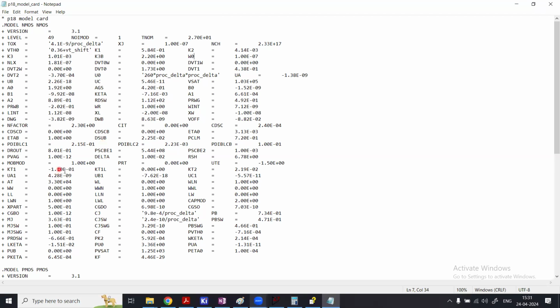But that's it. Now you can see that from these parameters, you can extract the mobility of the charged carriers for NMOS, which are electrons in NMOS. You can get the value of Cox, which is basically epsilon ox divided by Tox. So that's the oxide permittivity divided by the oxide thickness, and so many more.